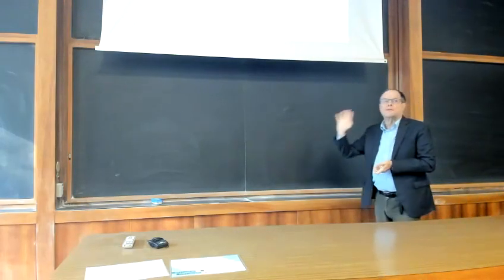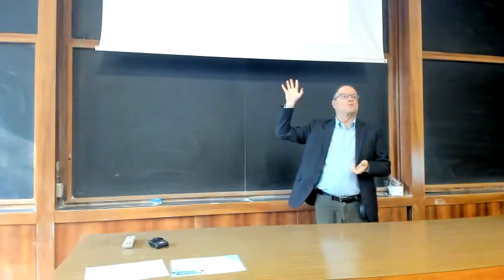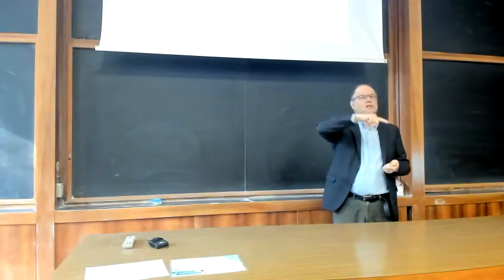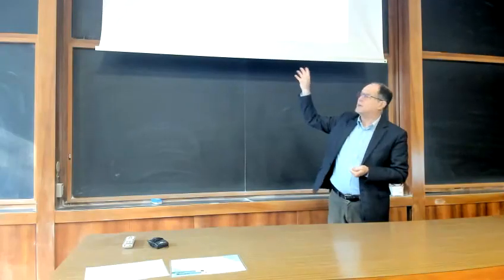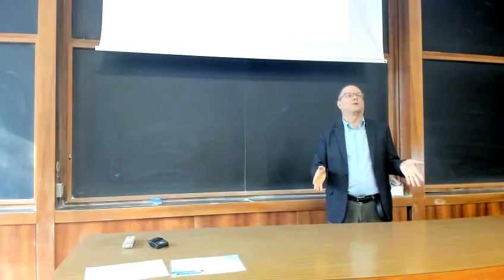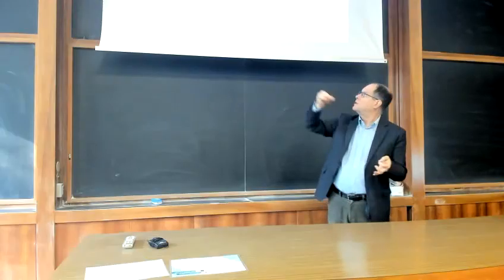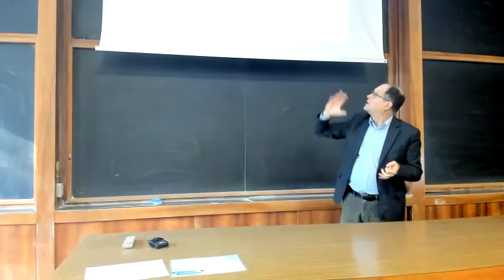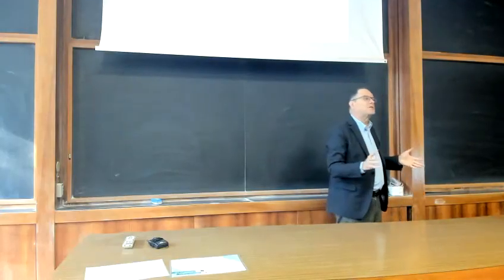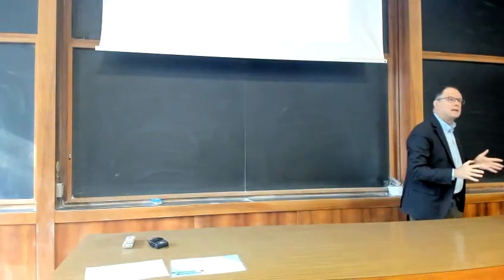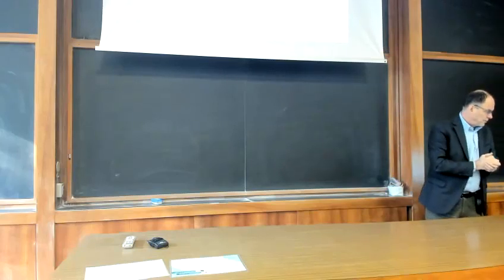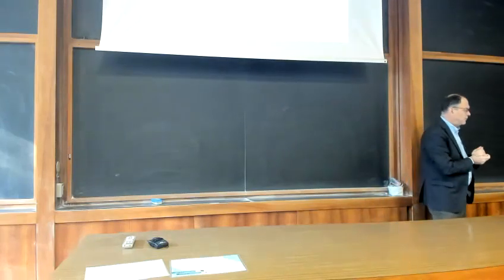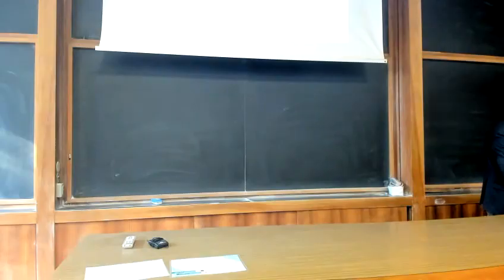So if you have followed me so far, this corresponds more or less to the load settlement curve that I showed you in the first slide this morning. Okay? So a continuous increase of the load, a continuous settlement, you never reach the definition of a full bearing capacity, and this is what you typically expect for a compressible soil. So we have understood, let me go back to this slide.